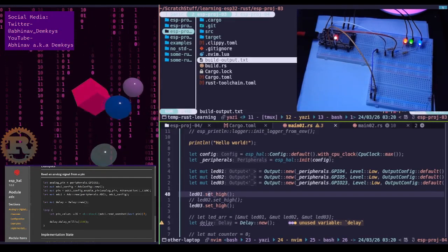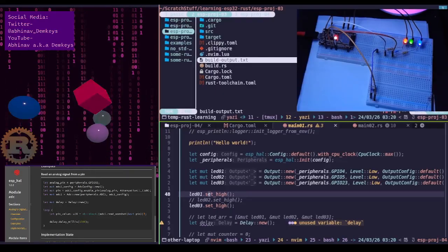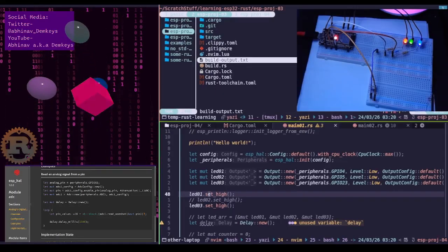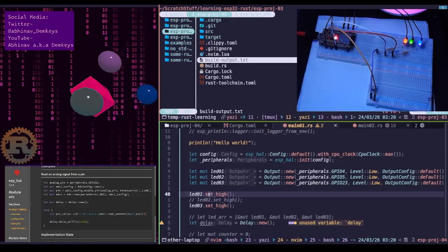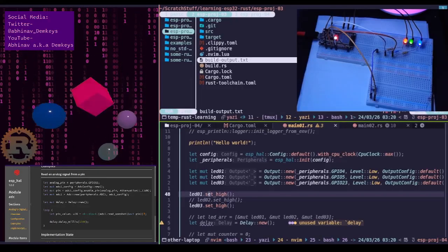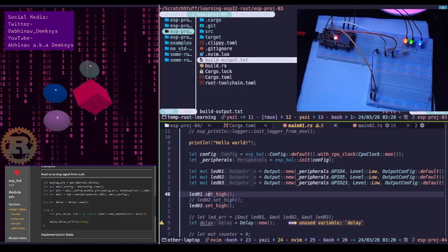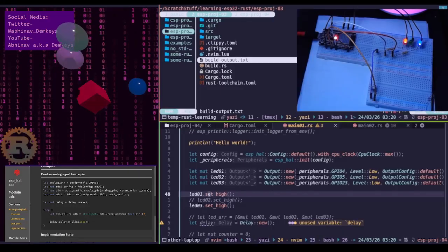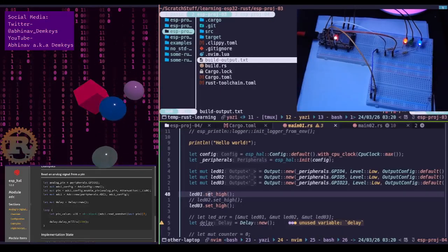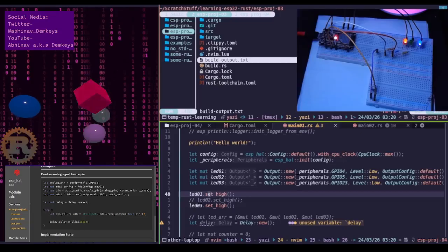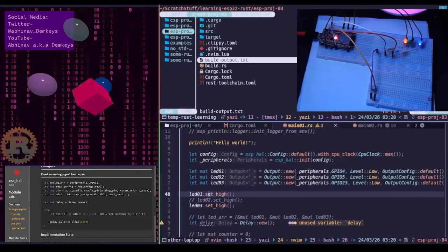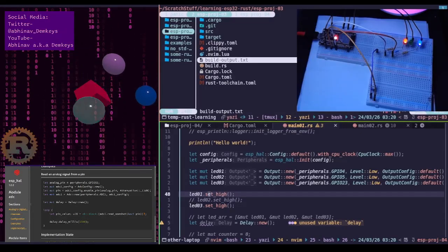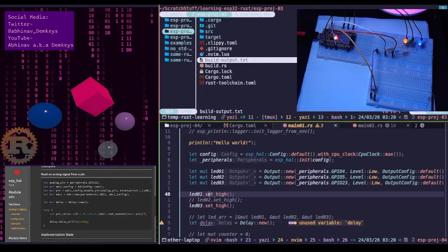One issue is definitely that the tip is not hot enough. Another issue is that it has become too hot and apparently the surface has oxidized, and that's why it's not transferring heat very well.